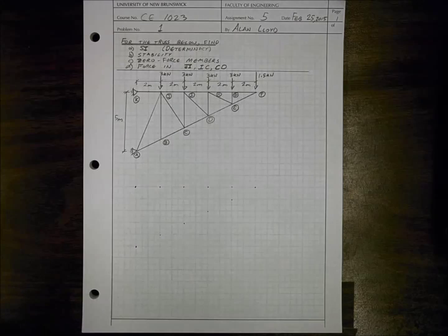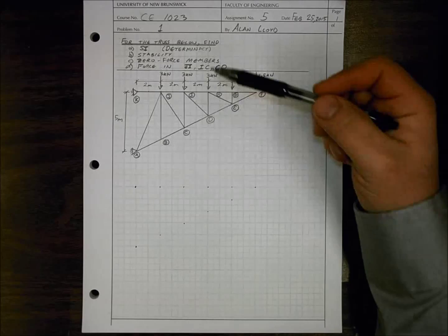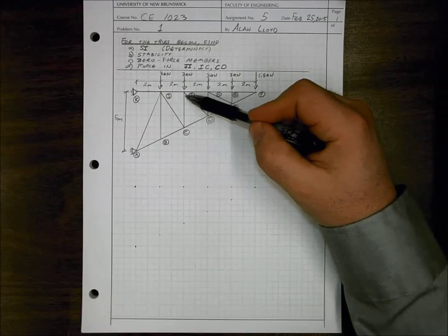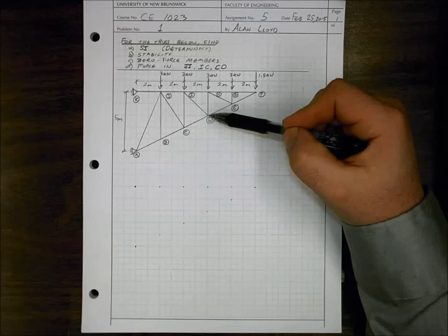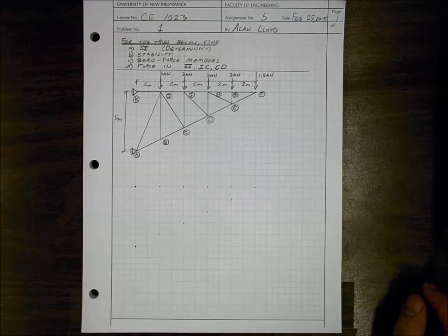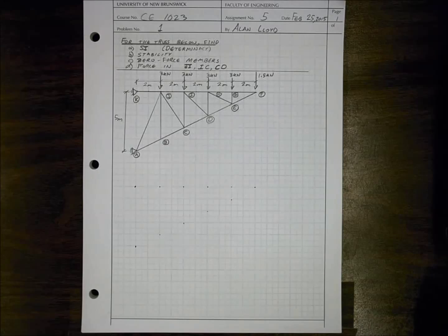So this is a truss where we're asked to find only certain member forces, the forces in JI, IC, and CD. Here's JI, IC, and CD. This, to me, implies that we're going to use the method of sections to rapidly find the information that we need without finding extraneous information, including things like support reactions or member forces in other members framing into other joints.